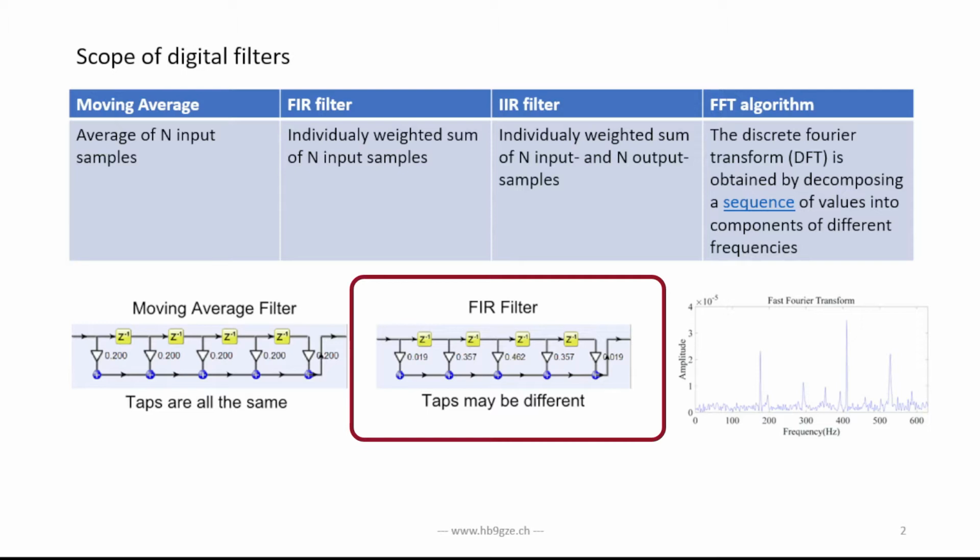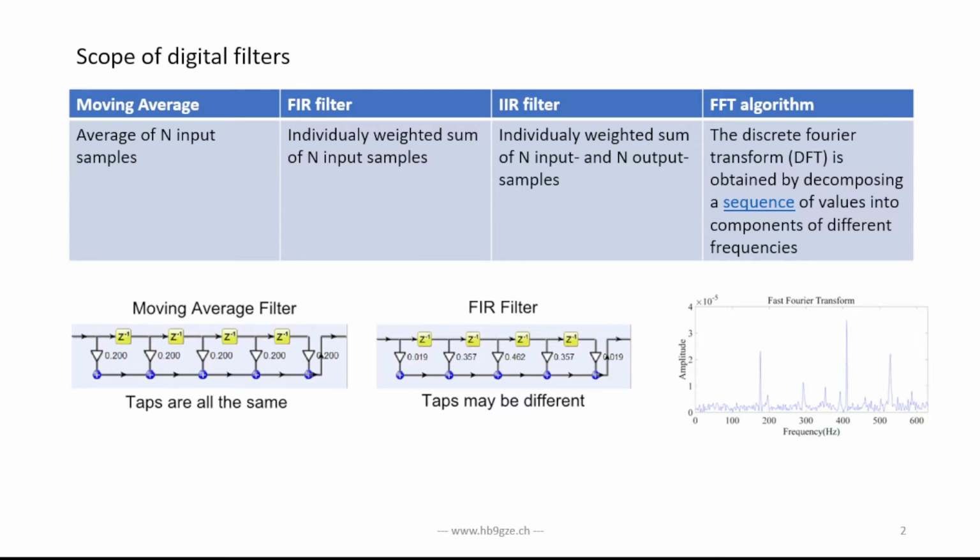And we saw before, this high performance low pass filter I've designed there has 129 taps. That means it uses 129 sampled data to generate the output. So it takes computation power, really. That's FIR, finite impulse response. And IIR filters we talk about in a minute. The difference from FIR to IIR is that you also take the output and feed it back into the calculation. We take a look at that in a second.